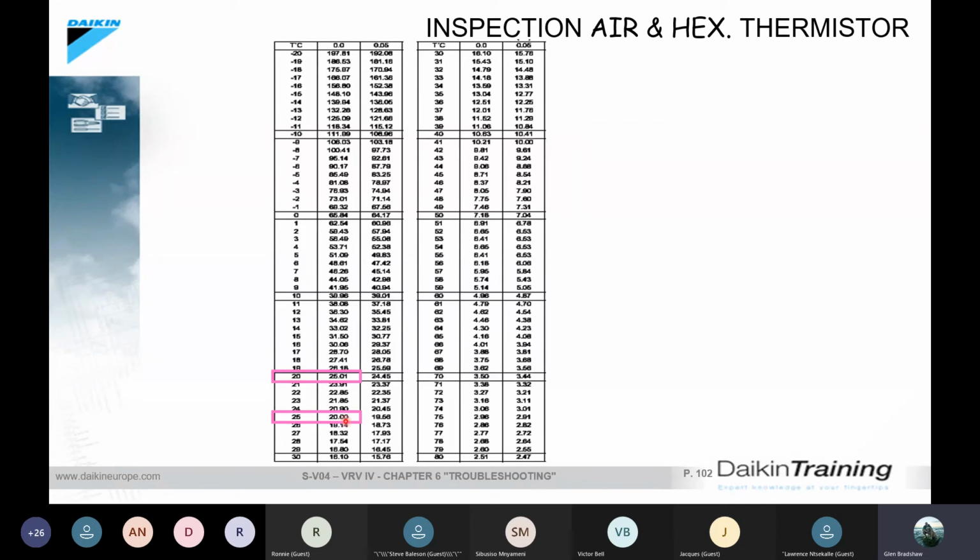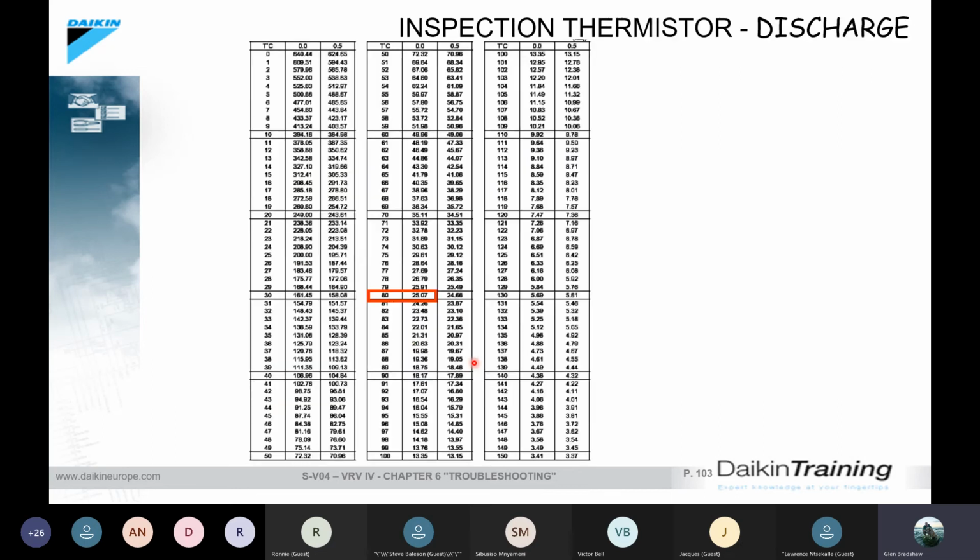Okay, and these over here are 20 kilo ohm thermistors at 25 degrees Celsius, and they are the inverse at 20 degrees. And generally, we often find ourselves in this band over here. So we know that 23 and 22 are pretty close together, so we can always get a good estimate with these 20 kilo ohm thermistors as to how accurate they are, because most times we will find ourselves in this area. But this is a table for it over here. And basically, if you don't have the app, this table is also very useful to help you determine what the resistance should be.